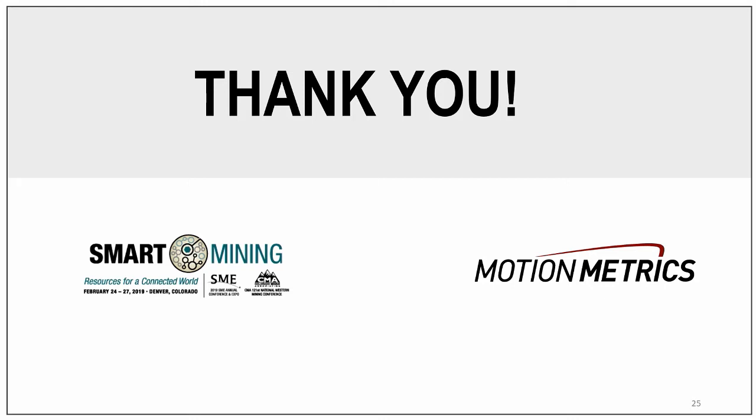Okay, very good question. What I presented here is 2D, a single high-res analog camera, because we have had it for years on the shovels. What you are referring to, 3D, is the ideal approach. With the 3D sensor I showed you, if I wanted to go to many mining shovels today, I would prefer that because the camera is high-res and I am doing 3D measurement. The part where I use the bucket size for scaling is not needed anymore, because the sensor measures everything in 3D. What I presented here is 2D, a single camera looking at the bucket.